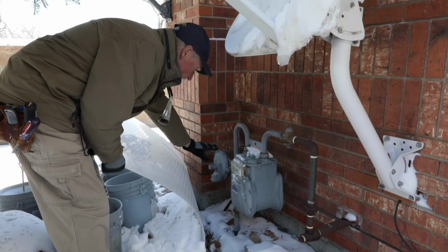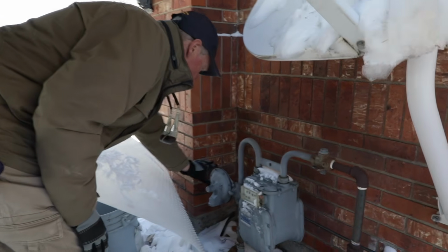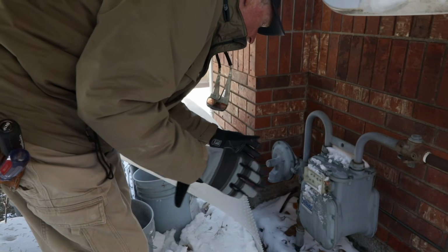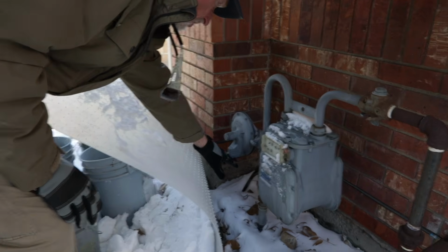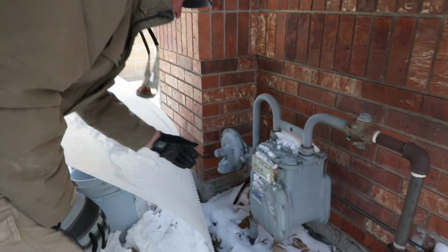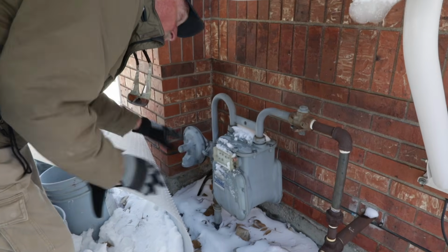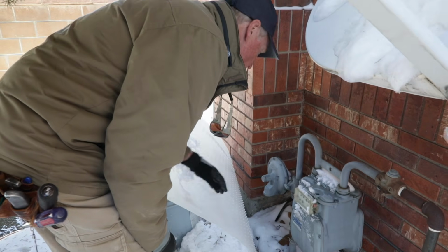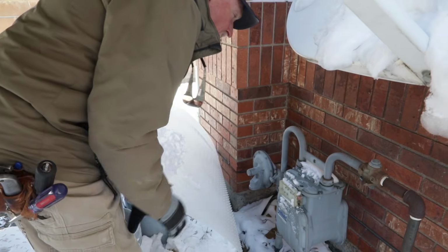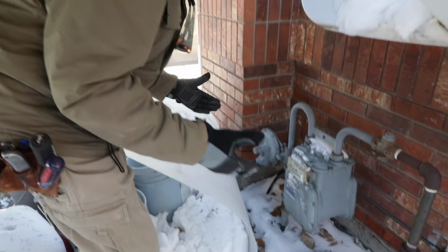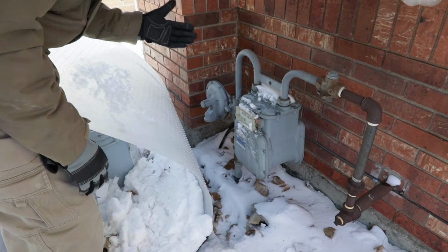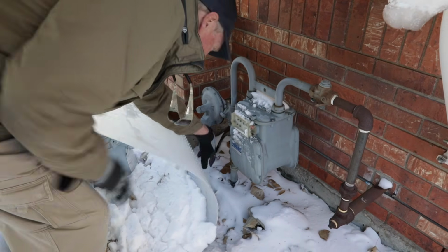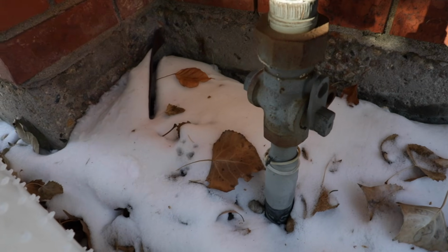Because this is a pressure relief system here, if there's a surge in the gas pressure to the house or something, it'll discharge that surge through the bottom of the relief here. So sometimes we have the good fortune, if you will, of being here just as it's releasing a little bit of overpressure out the vent here. So I'll let it do that, come back and check it with my gas detector and see if I'm actually finding a leak somewhere.